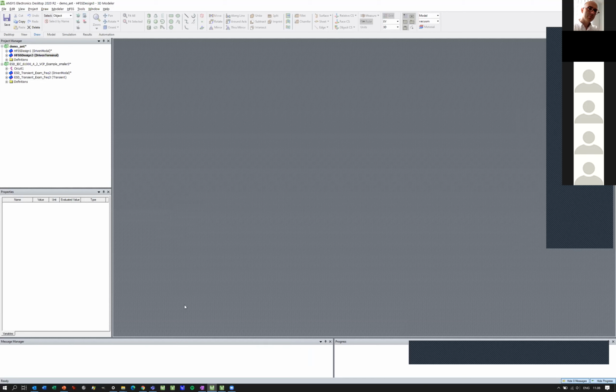Cleaning up the windows. So basically, when starting up something new, it's more or less empty. The first thing is to go to the upper menu and add a project. From the project, you can add different simulations. This is a user interface which is common for many different simulations, and under that you can open the more specific simulation packages. Today, we are mostly using this HFSS design, the first one.